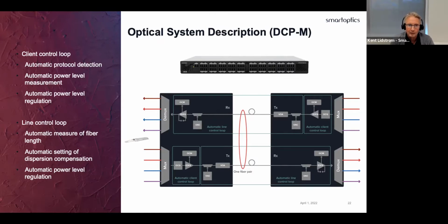But you can, like we do in this box, balance them unevenly on purpose by setting up a control loop where you attenuate each individual wavelength in the equalizer and look at the OCM to verify that we achieve the wanted power.